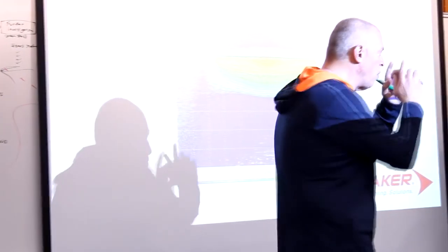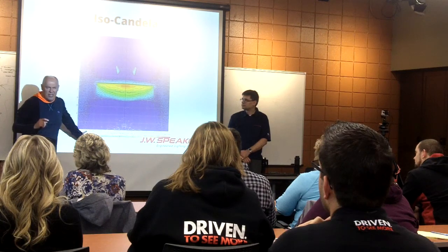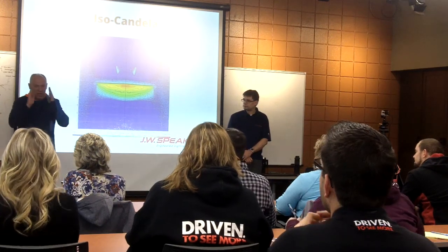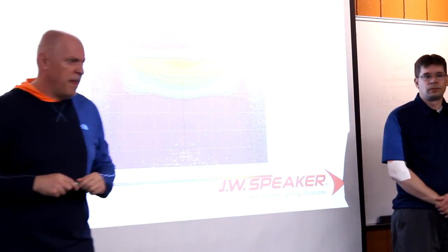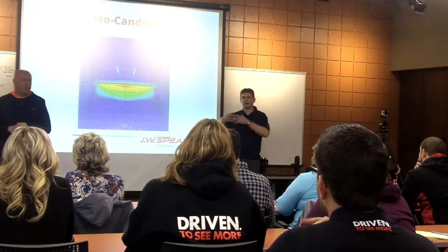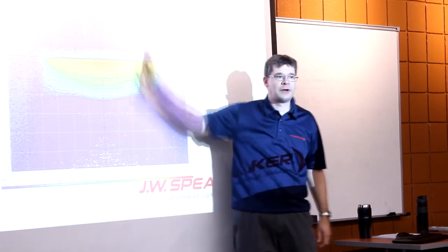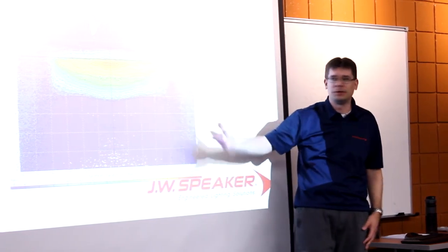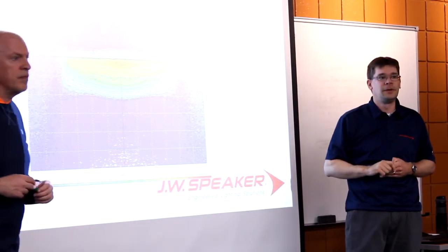So basically, when I'm looking at that, I see 60 degrees here. Okay? So peripheral vision is around 120. That's the reason why it's plus minus 60. So everything when you sit, that's what you see, and that's why we are using that window. Most of the time, all the lamps that we make and look at, the full pattern fits within that window. It's not like we're chopping off some of the main pattern and not getting an accurate measurement. Most of the time, it is completely within that window.